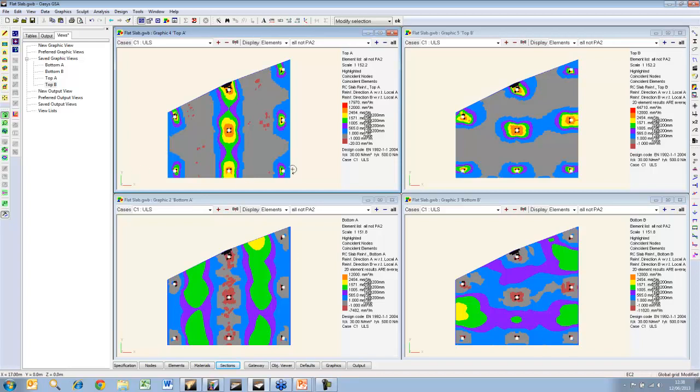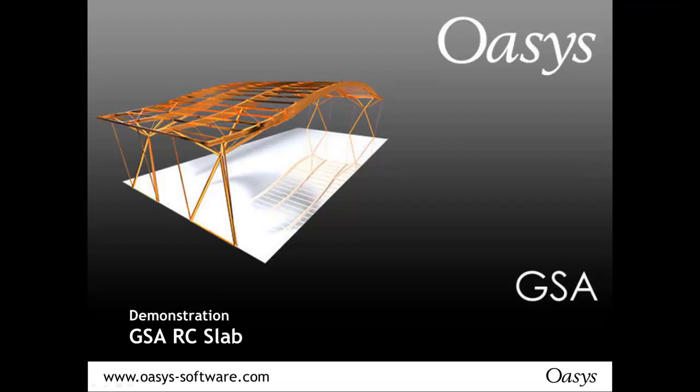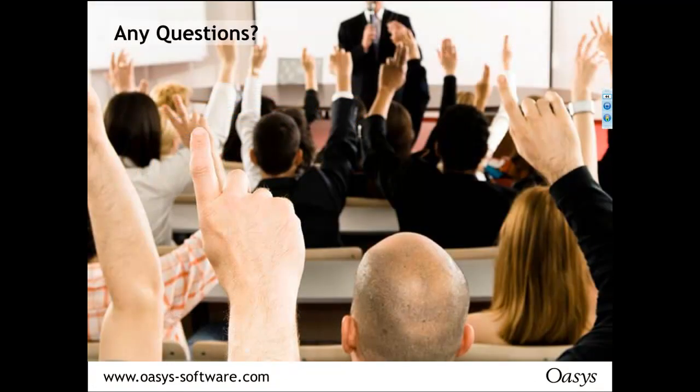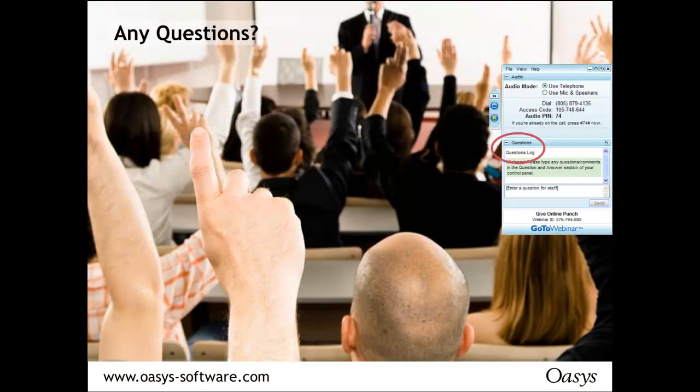Obviously, once you come up with a section slab thickness you like, then delete results, update the section properties, reanalyze the final self weight, and so on. Excellent. Well, that's a very quick introduction to the various concrete design capabilities in the 3 structural programs. Is there anywhere else you'd like to look in more detail at concrete design? So if you have any questions, do please type them into the questions box and I'll see about answering them.